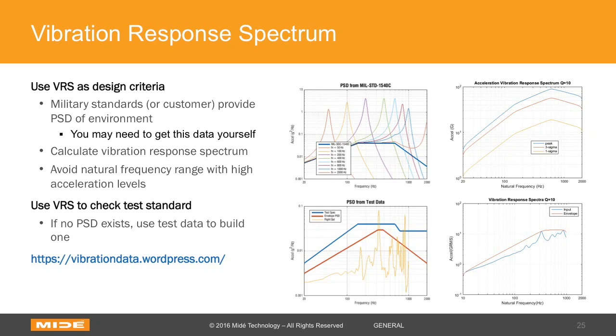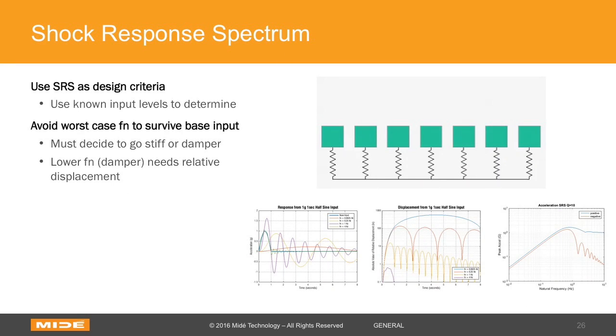So please check that out. Similar to the vibration response spectrum, you can calculate a shock response spectrum. Again, you'd use this as design criteria for a given input. You'd want to know what natural frequencies to avoid and which ones to design for.